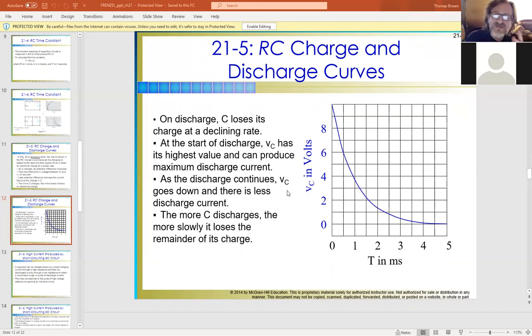And as you can see, it very much relies upon the actual value of the component. So as long as we do the ratios right, we've got to remember, for inductors, the time constant is equal to L over R. And for capacitors and resistors, it's R times C. And again, it's based on the way these things respond and where we're putting the -90 to +90 phase angles in comparison to the resistor and a lot of other things. But that's what we're going to be examining coming up.